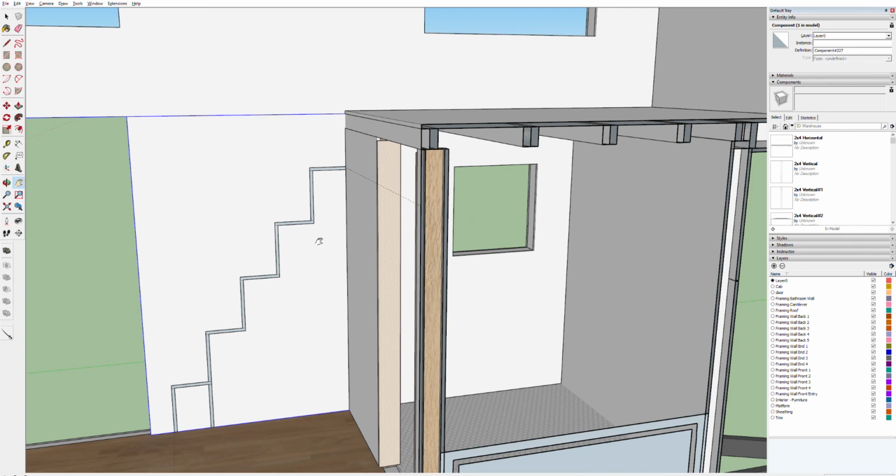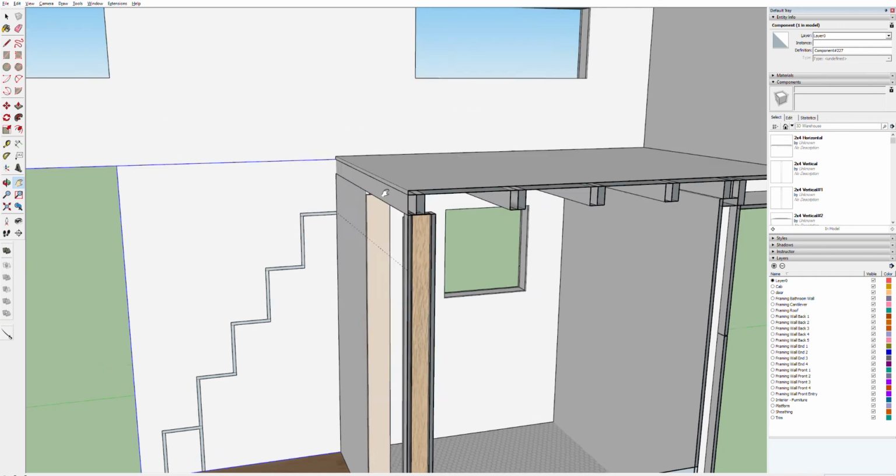So the idea, man, it's not going to work for this one, but the idea was to have a tall final riser so you could just kind of crawl into your knees. And these risers are all pretty tall. And this is eventually going to be a kid's room, so I think that's going to be okay. But the idea is if you have a tall riser, somewhere in the 14 to 16 inch range, maybe a little bit higher than this, you can very easily just kneel up onto here and crawl onto the loft. Whereas if you had a riser within 8 to 10 inches of the total rise height of your finished floor, it wouldn't be natural. You'd have to go up and then kneel back down onto your knees. You're not walking up onto this on your feet because the ceiling is going to be too low up here.